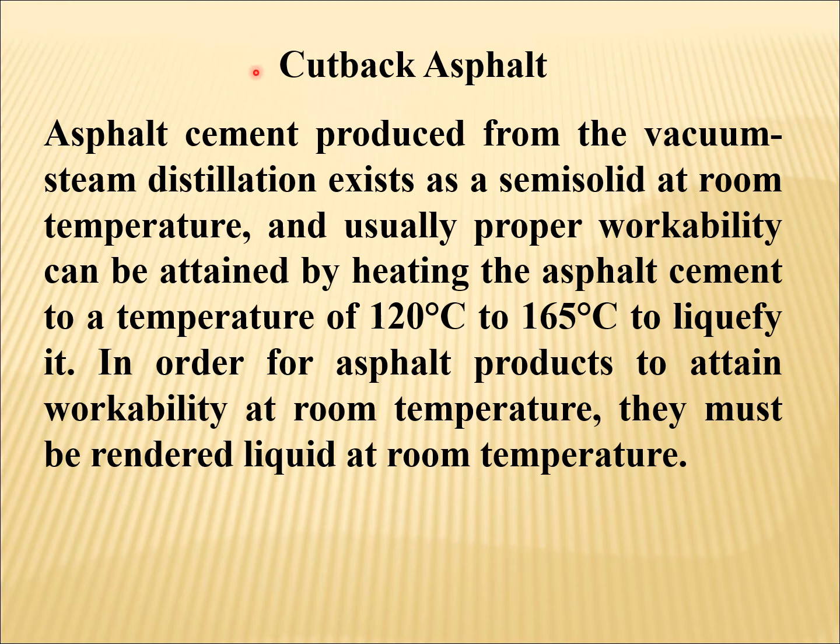Okay, now we are going to discuss the cutback asphalt. Asphalt cement produced from the vacuum steam distillation exists as a semi-solid at room temperature, and usually a proper workability can be attained by heating the asphalt cement to a temperature of 120 degrees centigrade to 165 degrees centigrade to liquefy it.